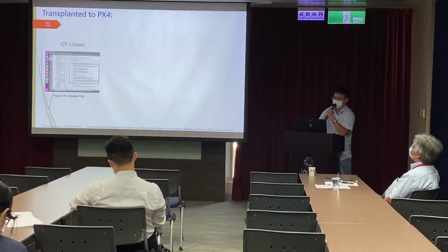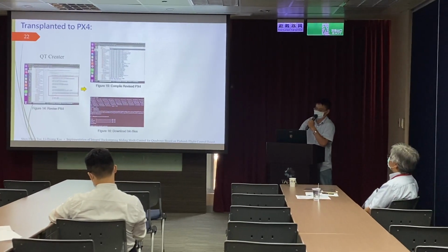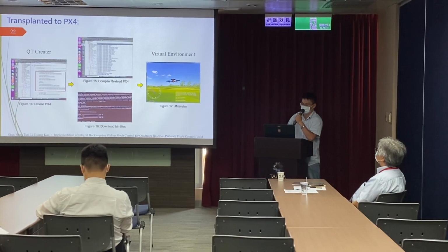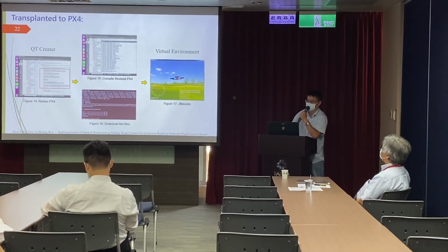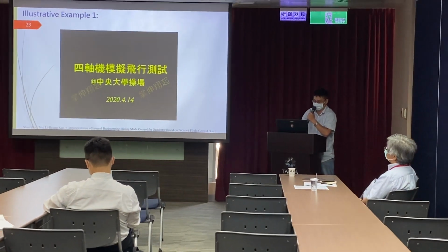So the IPSMC is implemented using Qt Creator, then GCC compiled it, and it was burned into a Pixhawk. And we use JMAVSim as our virtual environment to examine its performance. As it turned out, let me show it to everyone.